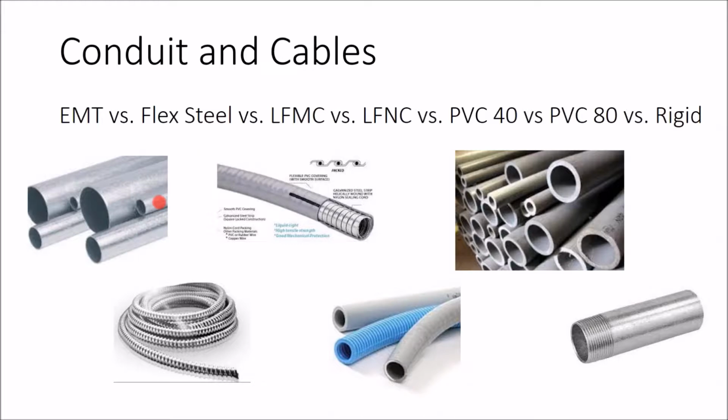And they say there's this rule that DC wiring has to be in metal conduit, so that if it arcs, it'll arc onto the conduit and ground out. And it's like, wouldn't that mean a plastic conduit might be a little bit safer, because you don't have this potentially energized metal conduit if there's a problem with your grounding system? No, what the metal conduit is for is to prevent a rodent chewing through the conduit and into the cable. A DC cable can cause fires in that circumstance a little bit easier than AC can, so DC has to be more protected than AC.